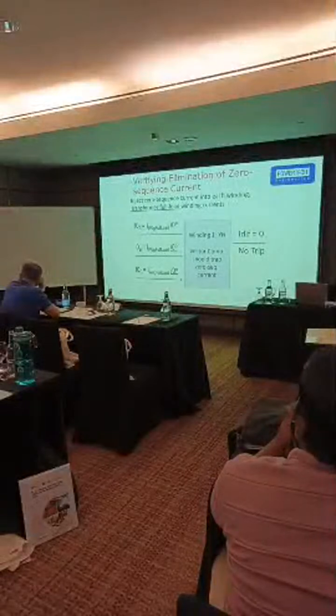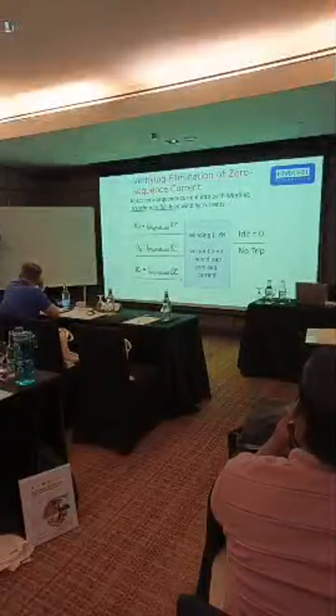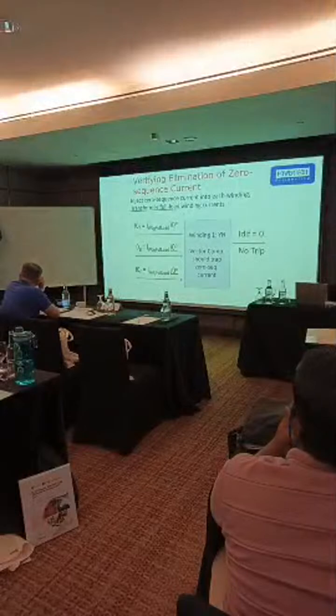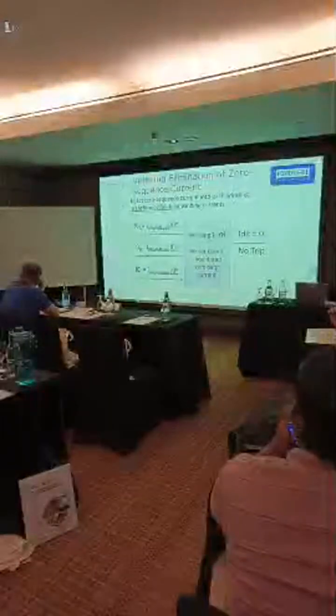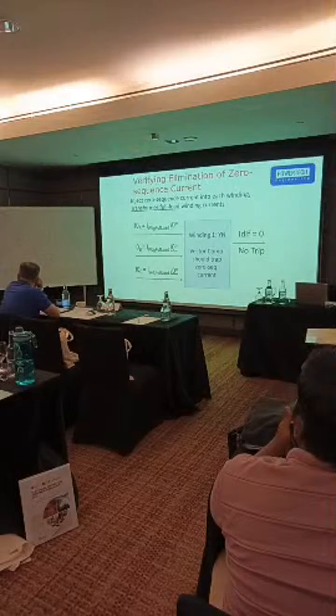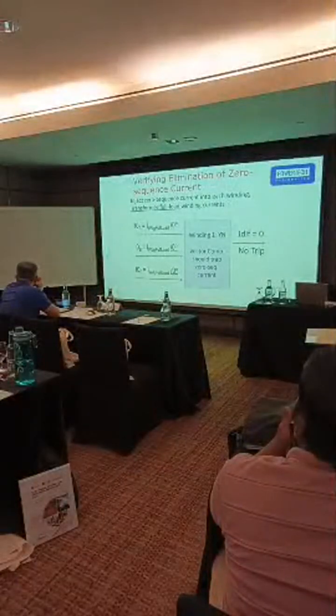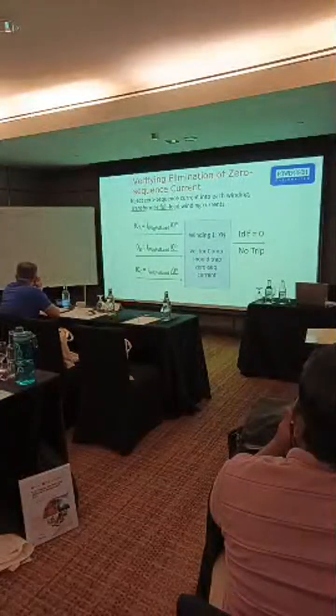Then the rated current was 0.73. I am talking about secondary current. It is 0.73. It might be different also. It is just for calculation purpose. Maybe I do not remember, then it will be wrong. Then what will be the pickup current of the HV side?